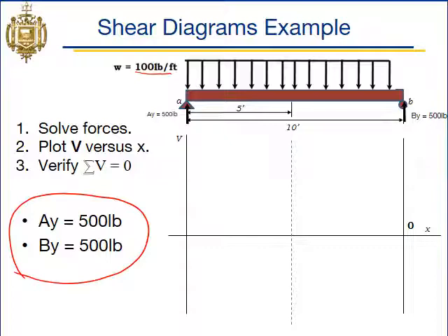free-body diagram, and then we'll start our plot. As you recall, when we do static equilibrium to find reactions, we resolve our distributed loads to a single point load so we can do our moment equation. But when we do our shear and moment diagram, we have to get rid of that point load and put our distributed loads back on for the plot, all right? Because the plots will end up being much different if you don't.